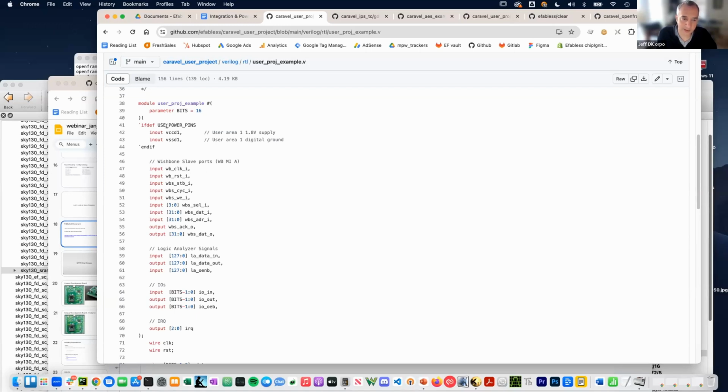If you don't have power in your Verilog and you don't have the hooks, you'll get a design that looks like the cell has been placed and implemented, but the power connectivity hasn't been made to that macro. So check your designs to make sure that power is indeed made to each of your macros.